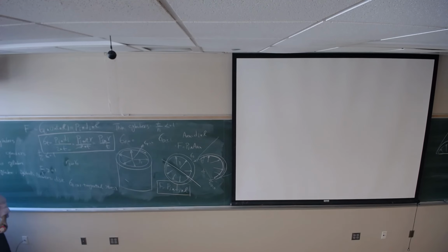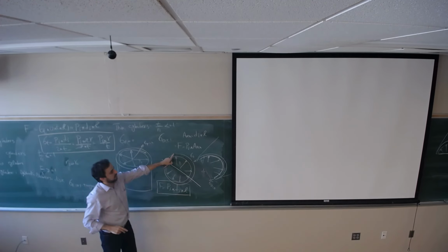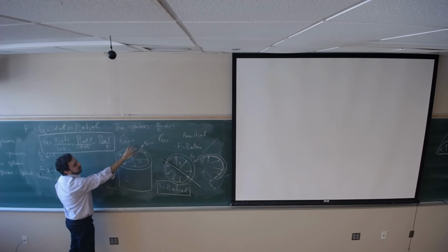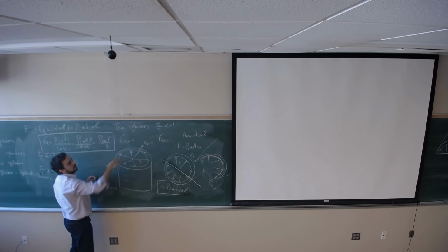So we only have tangential stress when we have a thin wall cylinder, sigma r equals to 0. Now, think about a pressure vessel where we have a cap at the end.